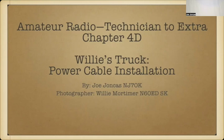Actually, you can buy boat standards, you can have up to 18 inches, but you want to make sure that there's no way for that wire to get shorted. Because if it shorts, that battery can put out 1,000 or 1,500 amps, and that wire will immediately go up in flames. And it's not a pretty thing.